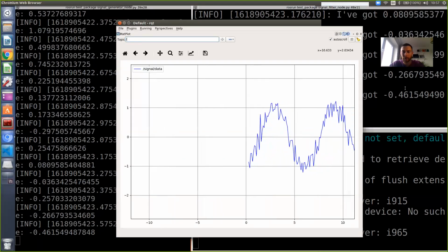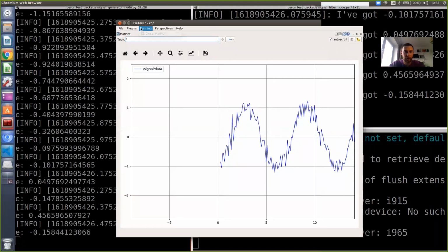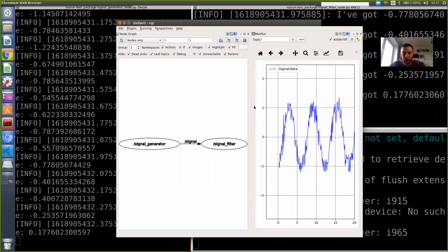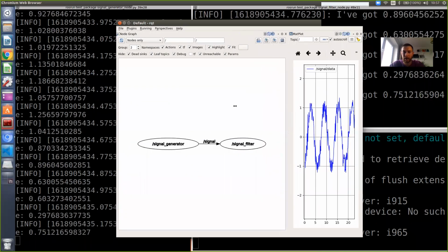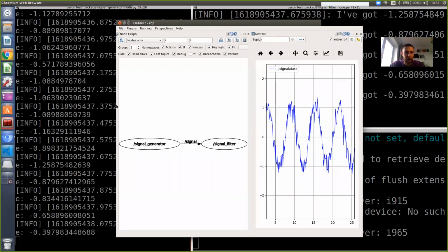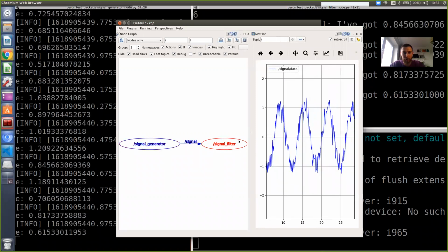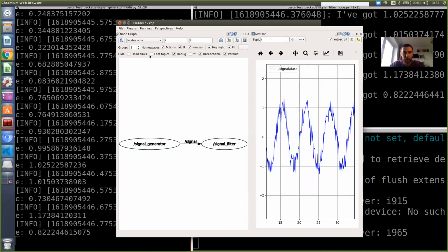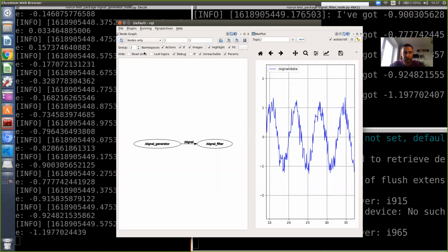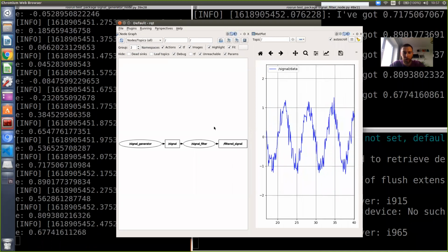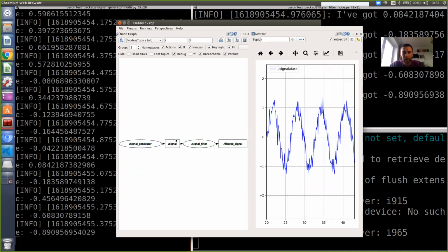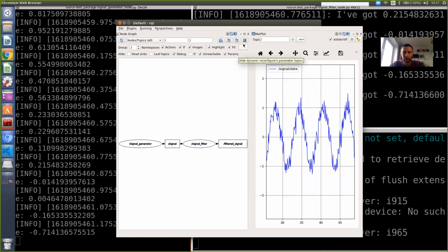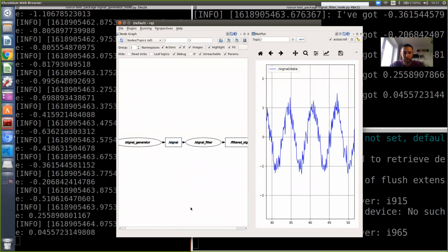And now let's first start from seeing our rqt_graph. You can see that we can have both within some window. So this is a really convenient tool. Now we see that there are two nodes. One is called signal generator, one is called signal filter. There is a signal topic between them. And if we again remove that and leave topics, and we choose nodes and topics, we can see that signal filter reads the signal topic and publishes the filtered signal topic. Let's now close it. I hope it was visible for you.